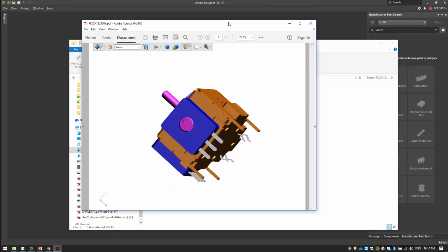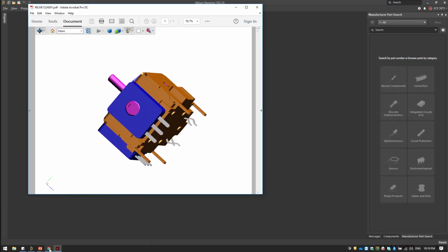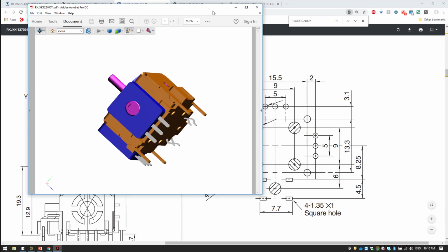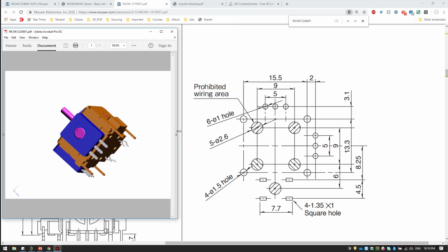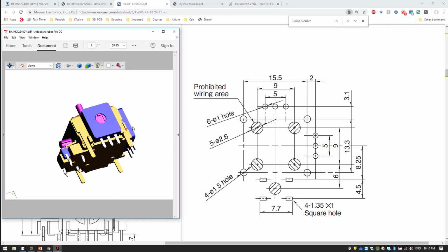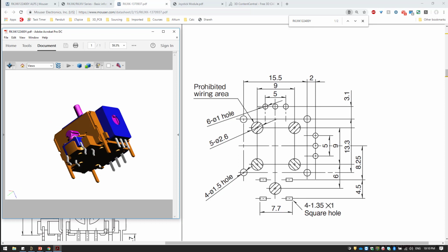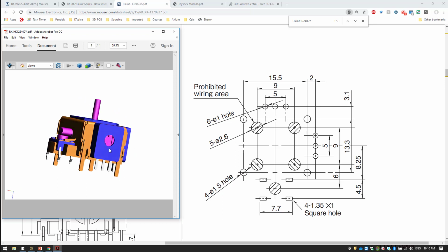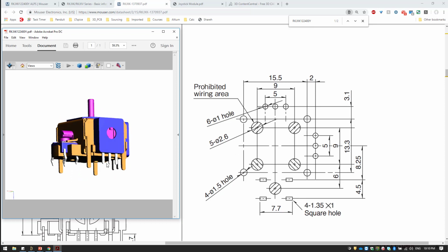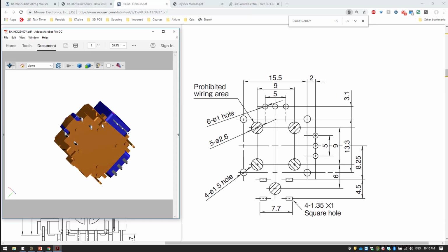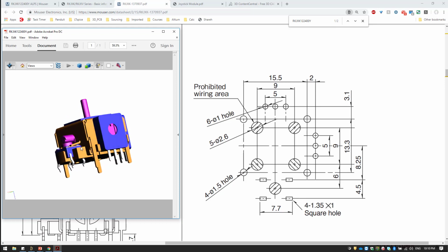Now let's take a look at the drawing they provided in here. So let's put these side to side and take a look at that, just to understand what's going on. It's very important to plan the component and understand the mechanical dimensions of it before you start doing the footprint, especially for a slightly complex component similar to this one. This is not a straightforward component. Like connectors, it is very easy to put a footprint for a through-hole connector because the spacing is known. It's very simple. Even if the connector has 100 pins, it's easy because they are all aligned.